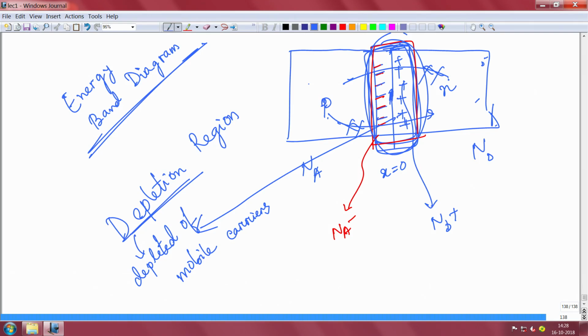So, here we will wrap up today's session. We introduced the PN junction, and before that we solved examples of the continuity equation, if you remember. Now, we have introduced the concept of the depletion region and how electrons and holes diffuse and recombine and so on. Next class we shall try to draw the energy band diagram of the PN junction, and so many things will become clear the moment we draw it. The conduction band, valence band, Fermi level, if you recall, we will join that diagram from the p side and n side and see what happens.